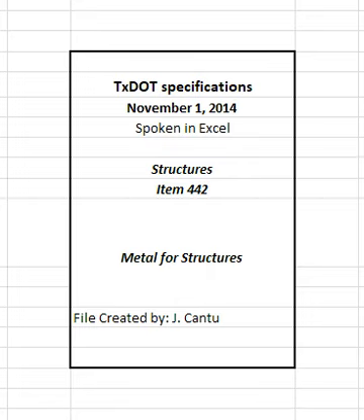2.1.2.2 Impact testing. Tension members and components of the following structure types, if more than 1/2 inch thick, and other members designated on the plans must meet the Charpy V-notch, CVN, requirements of Table 1. Base plates for roadway illumination assemblies, traffic signal pole assemblies, high mast illumination poles, camera poles, and overhead sign supports.